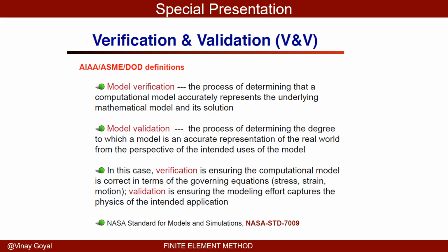On the other hand, model validation is the process of determining the degree to which the model is an accurate representation of the real world from the perspective of the intended use of the model. That means if you test a cantilever with an end load and you measure the deflection to be PL cubed over 3EI, that's what this model gives you. That's what model validation is. The model also gives you the same answer as the real test which you are doing.